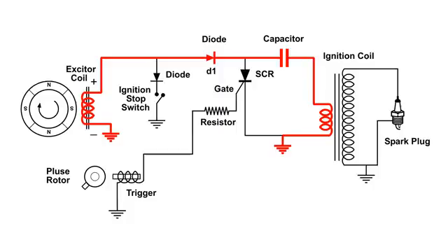And as we continue and get to another south pole, we have the polarity again, negative on the bottom and positive on the top, and D1 conducts, and we get a little more voltage in that capacitor. And again, we don't have anything until we get to another south pole, and we have a little bit more voltage put into that capacitor. And now we're coming up on another south pole, and now the capacitor is charged completely.